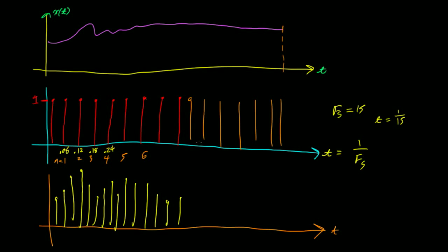actually let's just stop and recap. So aliasing basically means that if you are not aliasing, you've preserved all the unique characteristics of your original signal, right? If you do start to alias, then it's no longer preserved because you have one signal that is equivalent to another signal, right? That have very different frequencies. So our goal is to just maintain that uniqueness. Right? So if we want to look at this from a frequency perspective,